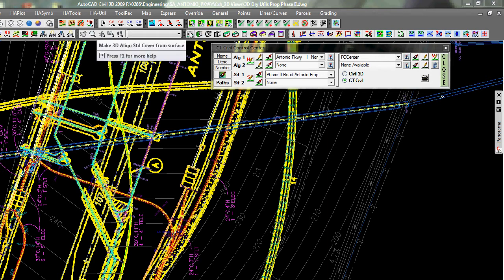It takes a 2D polyline and converts it into what I call a 3D alignment, which is basically a smart polyline. But it'll use the surface number 1, and it'll ask me a cover value, and then it'll automatically cut the surface to get the profile for that, weed it using a 0.02 criteria on the vertical, which actually works out quite nicely. So it weeds it and gives me a 3D alignment with the profile in place.